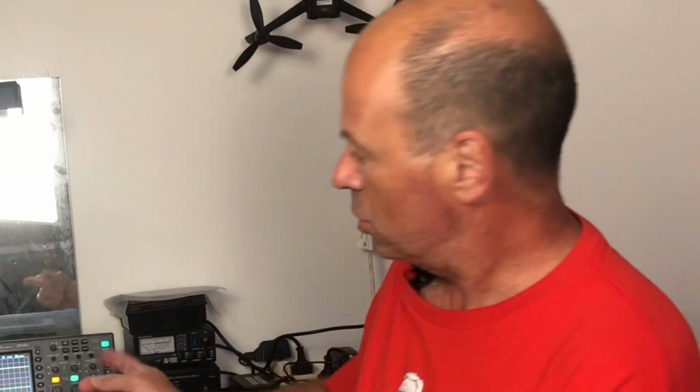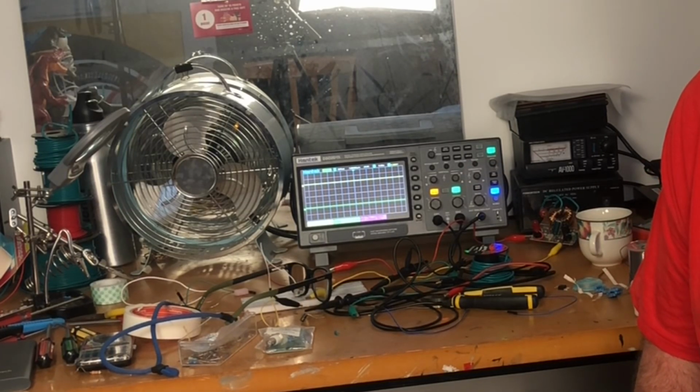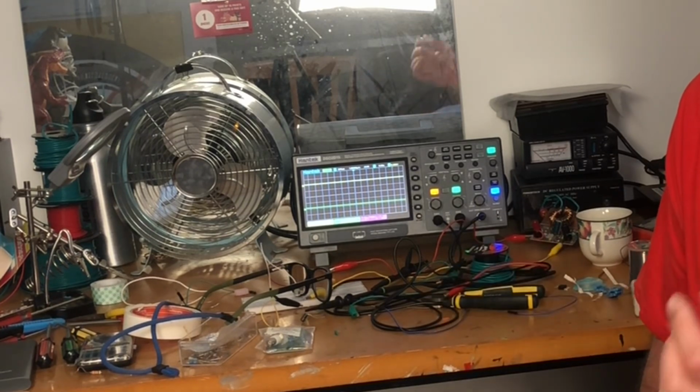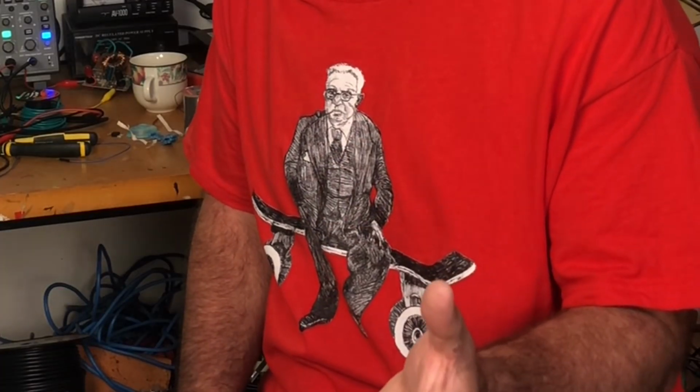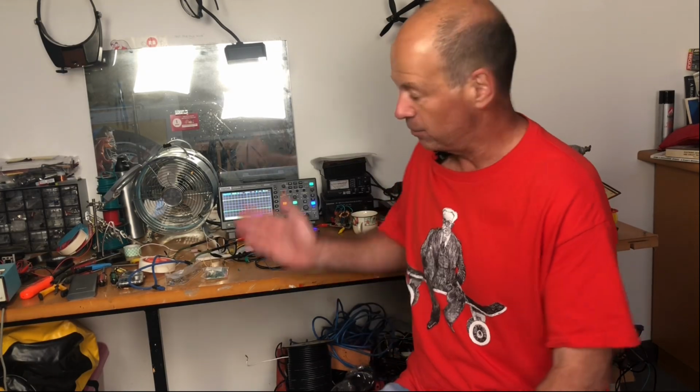Well, last night was a complete disaster. Stayed up till nearly midnight, trying to get a circuit built so I could demonstrate to you how that transistor works, and just put a small signal in using the arbitrary waveform generator on my brand new Hantek scope, and didn't isolate the signal from the actual voltages in the circuit. Should have used a capacitor. Really dumb thing to do. And I have blown up the AWG, the signal generator in the Crow. So very sad that I've destroyed a good piece of equipment.